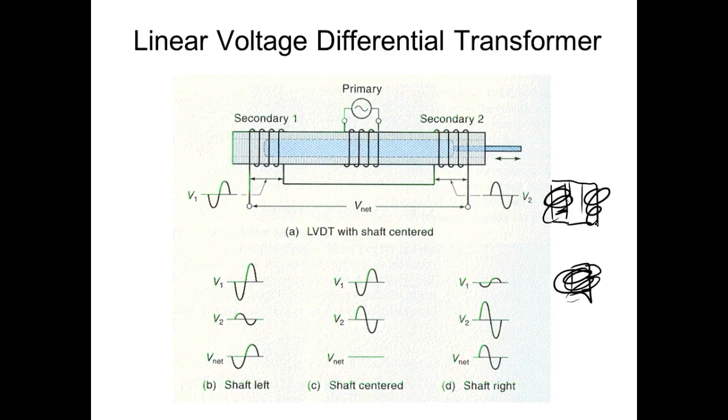Now, normally that makes no difference, because all we're doing is AC. So if I hook up an AC motor, it doesn't care about the phase, right? You understand? If I was going to fire an SCR through a transformer, then you've got to understand the phase. So pulse transformers actually put dots on the secondary that indicate the phase. Does that make sense?